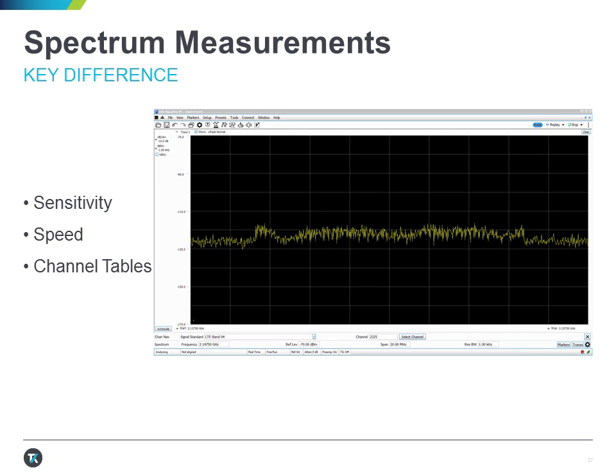The key challenge there is that very often when we set up a narrow resolution bandwidth, the speed of the spectrum analyzer suffers greatly, meaning the probability of intercept, meaning how much or how fast we can actually measure the spectrum, can be degraded by the narrow resolution bandwidth filter setting.